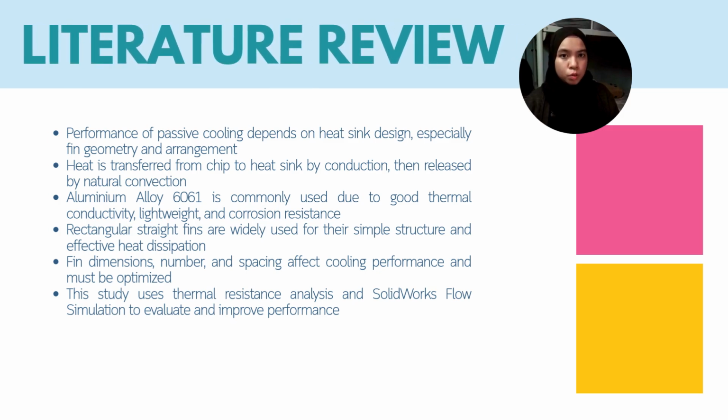For the literature review, previous studies show that the performance of a passive cooling system mainly depends on the heat sink design, especially the fin geometry and arrangement. Heat is transferred from the chip to the heat sink through conduction and then released to the surrounding air by natural convection. Aluminum alloy 6061 is commonly used because it has good thermal conductivity, is lightweight, and has good corrosion resistance. Rectangular straight fins are widely applied due to their simple structure and effective heat dissipation.